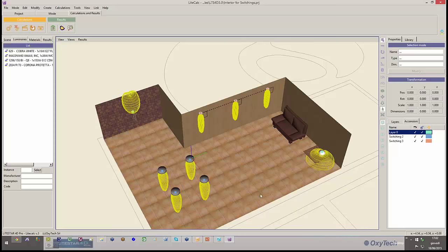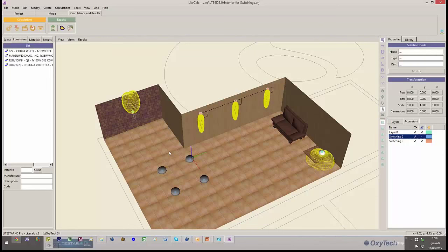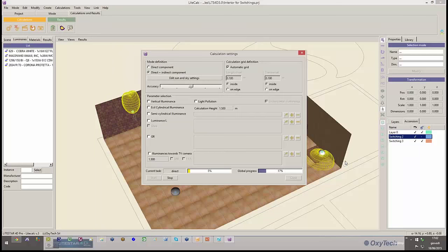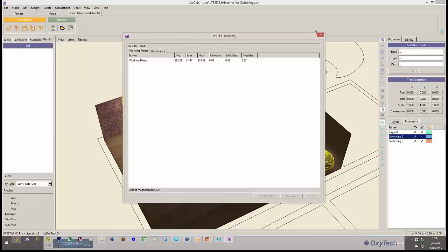So if I am in such a configuration, I mean with the photometric solid available, then it will be possible to immediately select or unselect, it means turn on or off the luminaires. So if we want to turn off these luminaires, we select this tag, and the luminaires will be turned off. So they won't have the photometry. At this stage, we can run calculation, and at the end, visualize the rendering and see how it works.